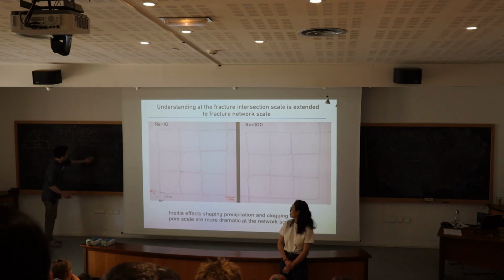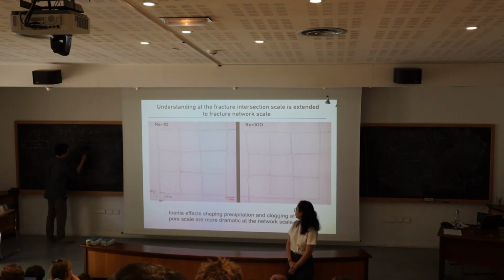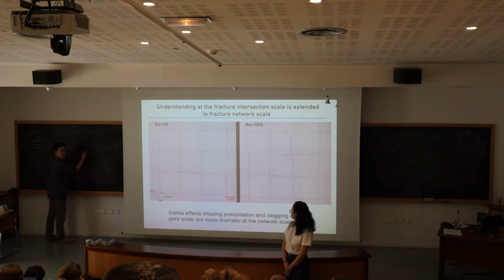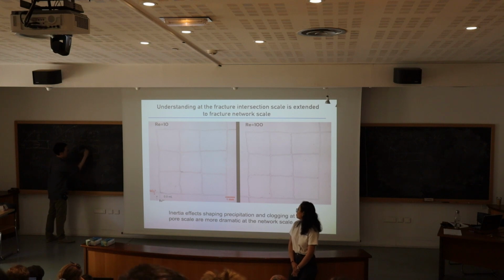Yes. I can send you a paper. In the recently published paper, we showed a single fracture with matrix. As you said, most matrix-fracture interaction models assume matrix diffusion. But what we showed is that even in the inertial laminar regime, there can be advective exchange. So solute can advectively get in near the fluid's fracture-matrix interface, which leads to enhancement of solute trapping, which can lead to a very strong tailing.